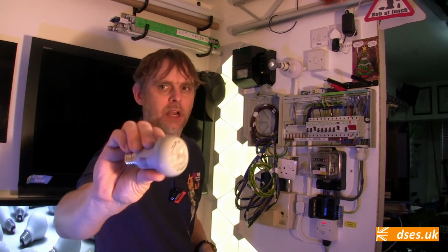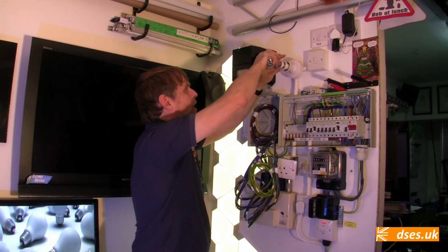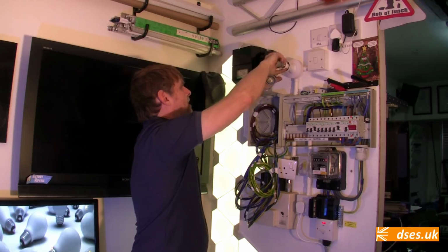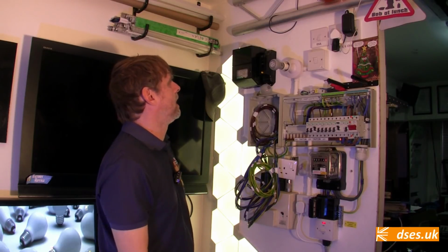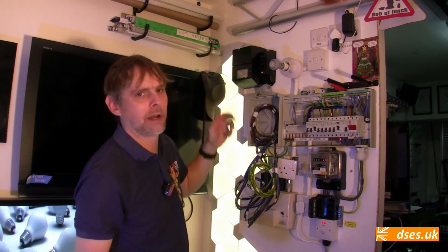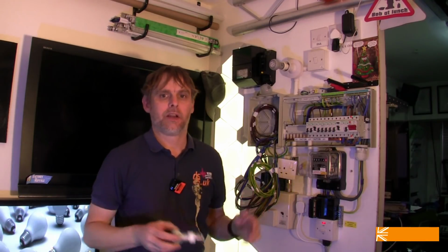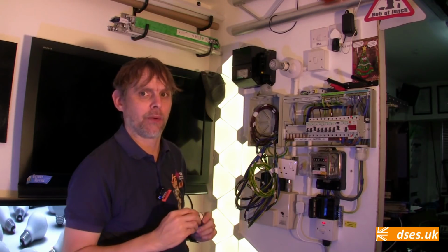Here I have a Tesco R58 LED lamp, and if we take our glowing GE lamp out and put the Tesco one in, we'll see how that current affects that. And there's nothing, no nuisance glow at all, and that's simply because the Tesco lamp has a different circuit which is not affected by this tiny capacitive current. Let's see if we can take some readings of the voltage and current on our glowing GE lamp.